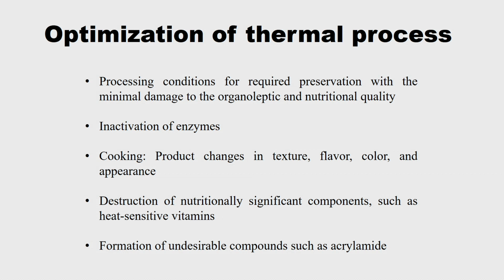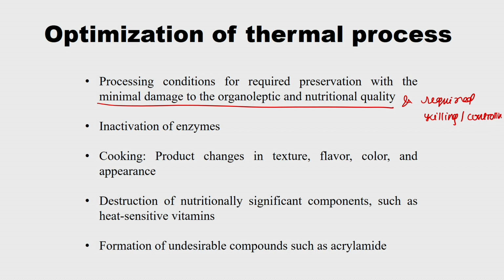Along with that there is nutritional quality damage also. So we are supposed to design a thermal process which will not damage the nutritional quality much, and which also has to kill the required level of microorganisms, right. So the optimization is something like minimal damage to this one and the required killing or controlling of microorganisms.